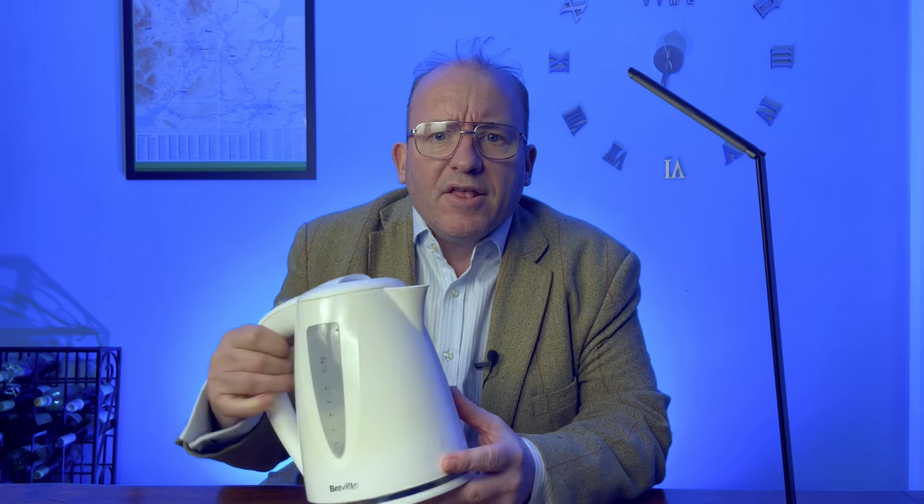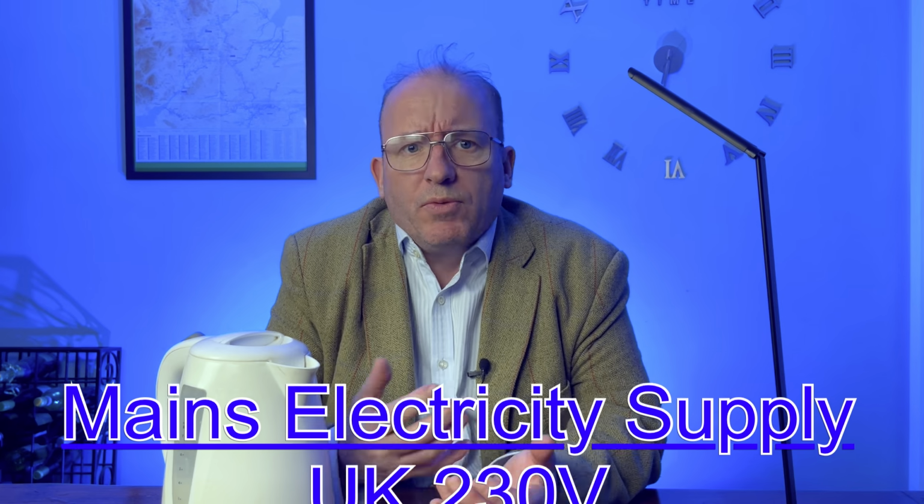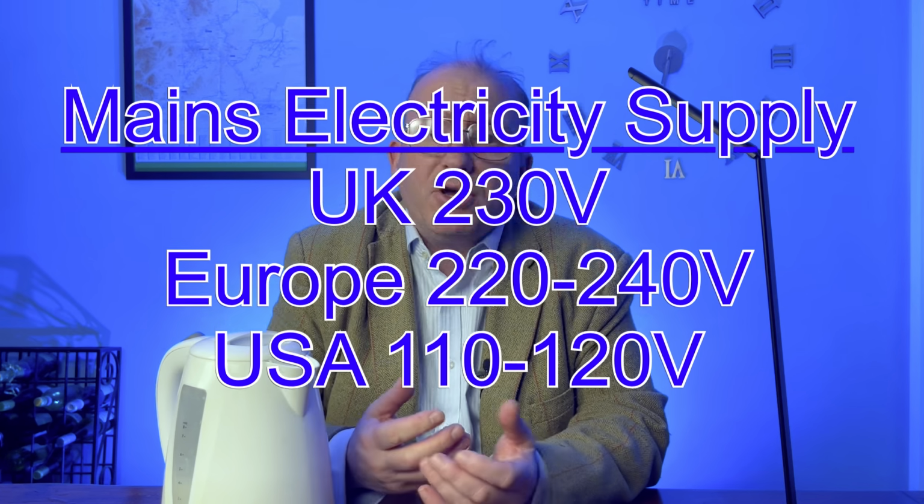What is its power? Well, power is current times voltage, which equals 0.6 times 12, which equals 7.2 watts. If you look on the bottom of most appliances, you'll find a power rating on a sticker. This one is 2,750 watts. This is my wife's kettle. In the UK, our main supply is 230 volts, which is similar to the rest of Europe. In the US, it's around 110 to 120 volts.